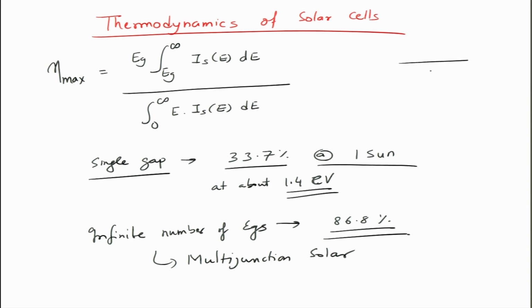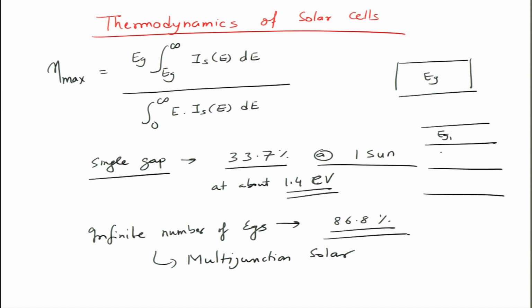One solar cell will have only one Eg, okay, but you can have multiple layers with different Egs, so that your Eg1, Eg2, Eg3 absorb the short wavelengths on the top and longer wavelengths lower down. You make a device of multiple band gaps, which can give rise to higher efficiencies. Of course, it's a design challenge for materials engineers, but theoretically speaking, one can achieve efficiencies as high as 80%, 85% if you are able to do good device engineering.